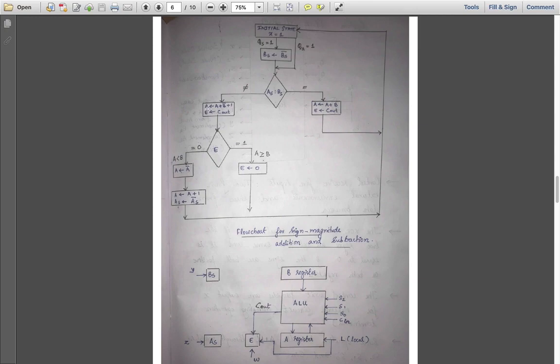So now the result is stored in the register A. That is being done here. A is being complemented and stored in A, and then the content of A is added with 1. These two steps denote the 2's complement of the result, because the current result is in the A register. A plus B complement plus 1 has been stored in the A register, so the result is in A. The result is complemented if no carry flag or overflow is set. Okay, so now you understood how you came up with this flowchart or algorithm based upon that particular example.